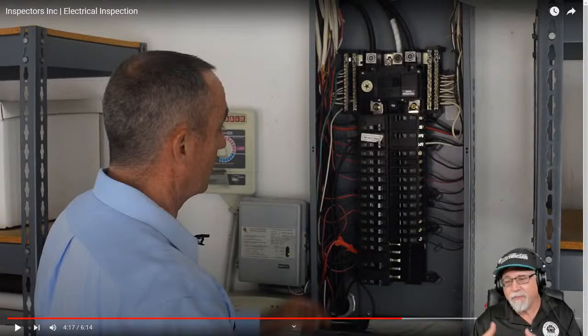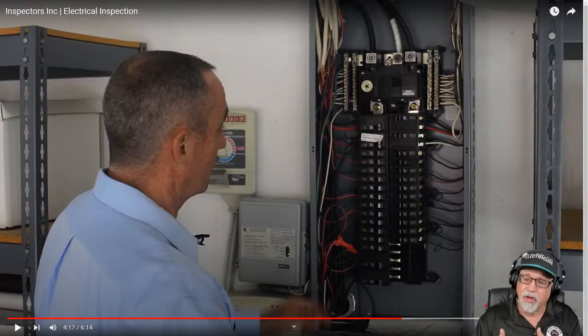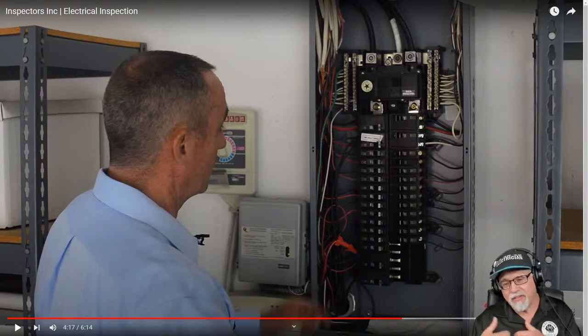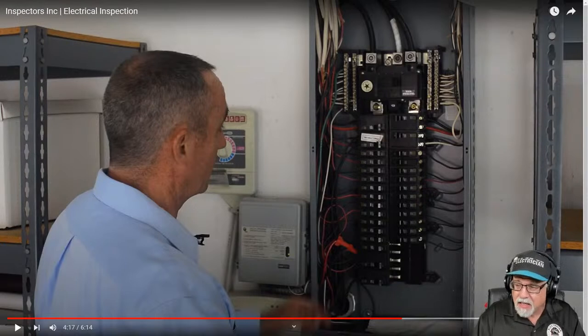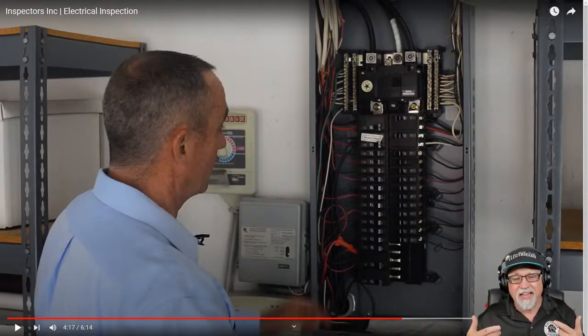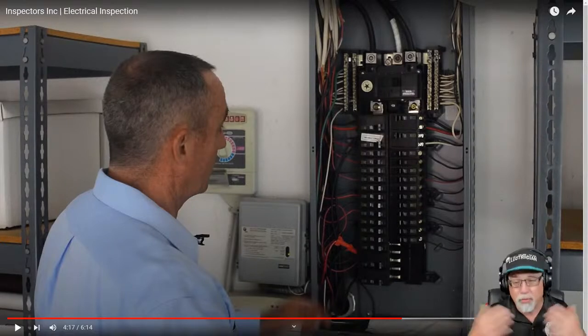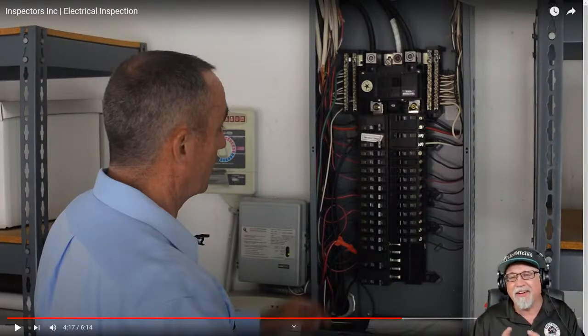So it might say 40 amp maximum overcurrent protection, minimum 20 amps branch circuit conductors. That means we're putting a 12 gauge, which is good for 20 amps, onto a 40 amp overcurrent device. The conventional logic would say you don't do that. Small conductor rules in 240.4(D) say you don't do that. However, there is an allowance in the code for doing that.